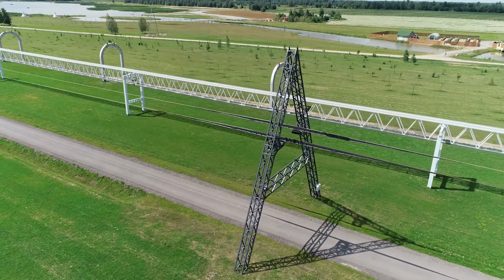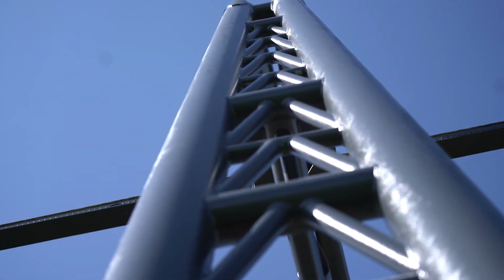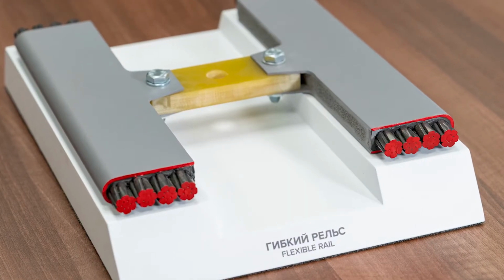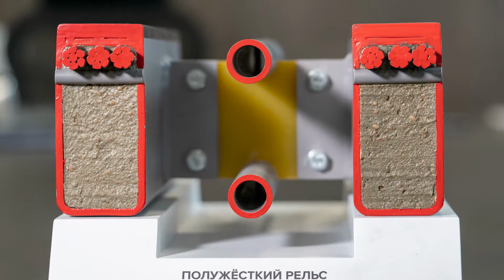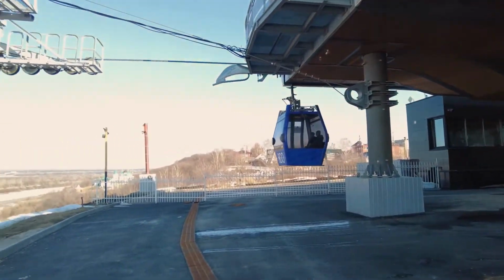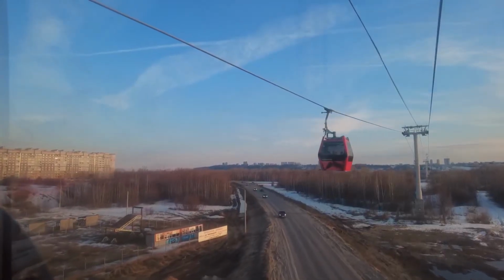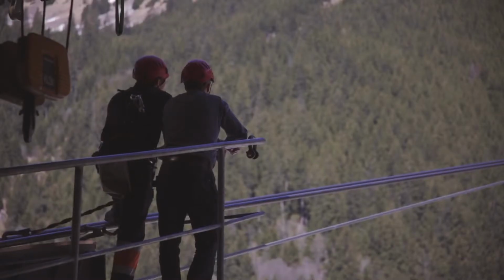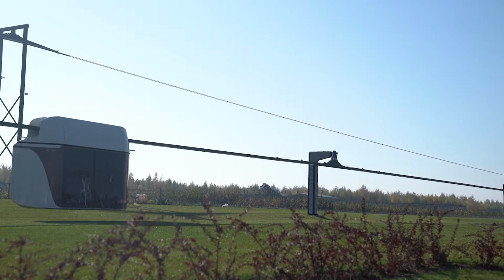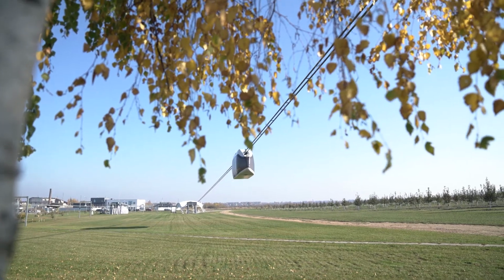The load-bearing string elements of the transport overpass have a tenfold margin of strength. They are resistant to vandalism and terrorist acts. The rail consists of steel reinforcement elements fitted in the core, a filler, and a high-strength housing, which increases its overall strength. As a track structure, cableways use only an ordinary twisted rope that is unprotected from mechanical and climate impacts. Cables of most systems known in the world need to be completely replaced with a frequency of 3 to 10 years. The service life of the UST string technologies track structure is at least 50 years.